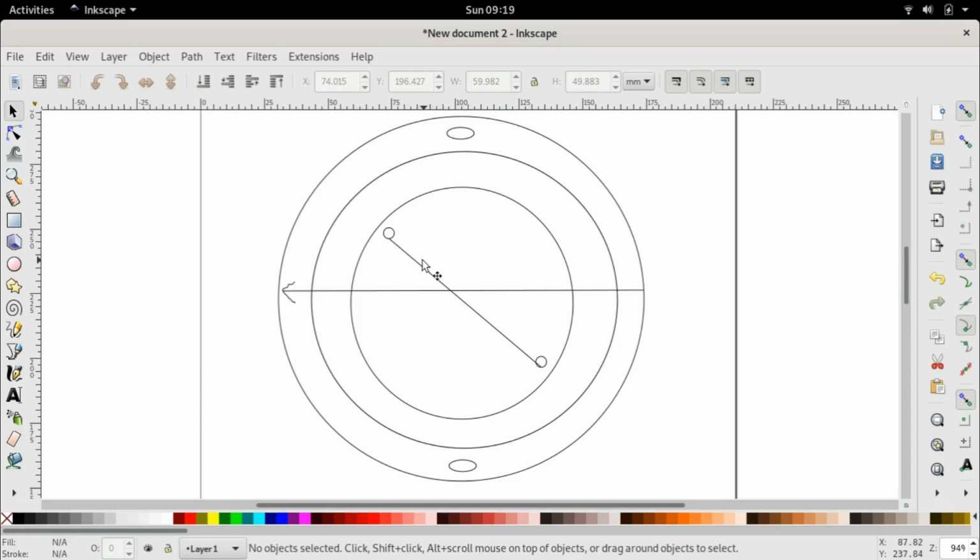Why? Because the entire stator flux cannot be, when is it maximum? When the stator flux is passing at exactly 90 degrees to the rotor axis. That's not the case here. There is an angle. That angle is not 0 degrees, the angle is not 90 degrees. The angle is some angle between 0 and 90. So this general case that we've considered is a case where you can say a projection of the stator flux with respect to the rotor axis is now the flux which is linking the rotor.